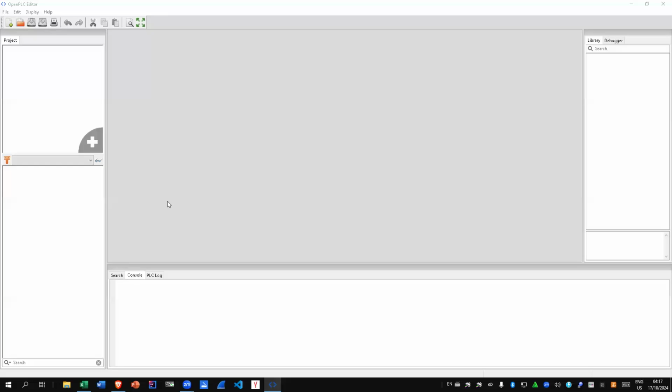We're recording this session. As you can see, the Open PLC is now working. The problem I ran into is the installer would not install properly. As you could see, there was a fault in the Python execution. Apparently, the 2022 version is not compatible with the 2024 version.